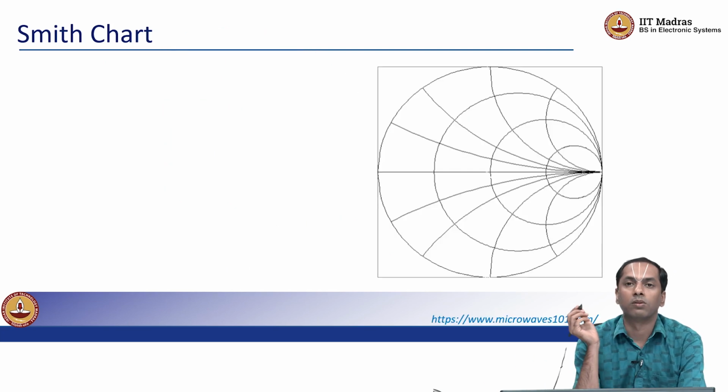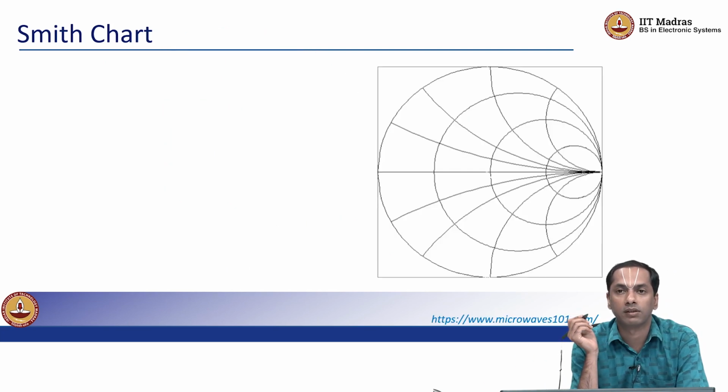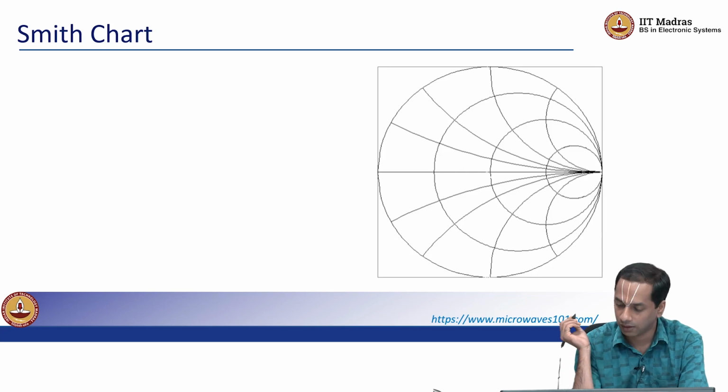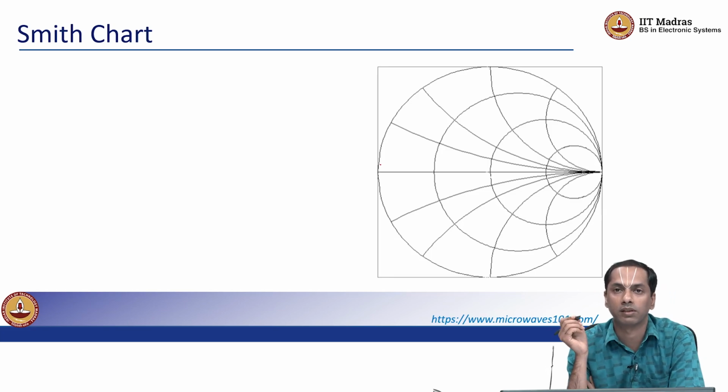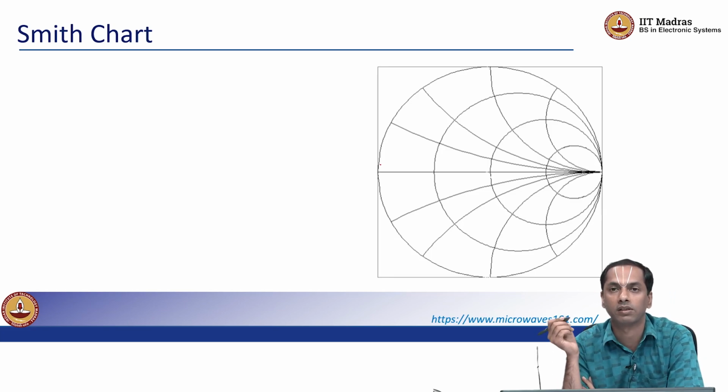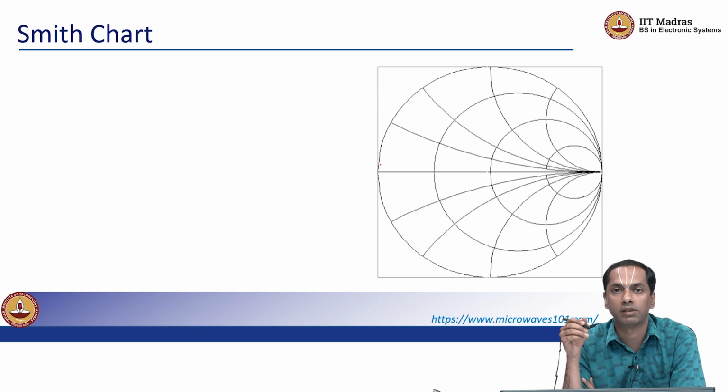Okay, so with that information in mind, this is how a traditional Smith chart looks, right? The reason I wanted to show this to you is that you can normally see these charts and you see curves drawn on them. When you have an inductor or a capacitor, obviously the impedance of these inductors and capacitors is a function of frequency. So you can actually plot impedances as a function of frequency on this Smith chart, right?